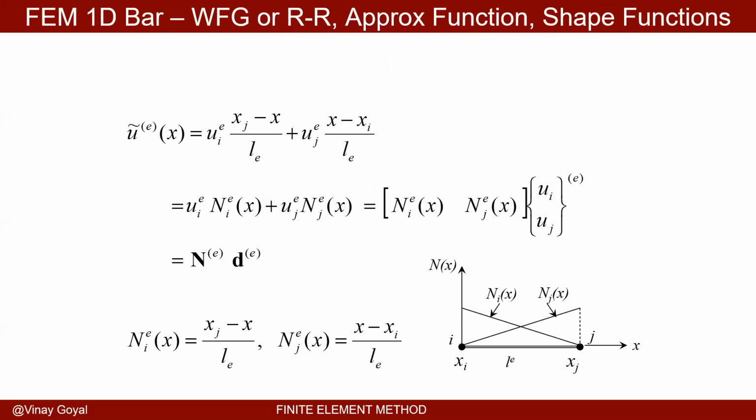So it is kind of convenient to plot them and see what's going on. Now, when it comes to finite elements, it pays off to write everything down into very simple equations. So here are the unknown coefficients. I'm approximating the solution over a domain, over the element E. And you can see here U_i^e is the nodal value U_i. This is the nodal value U_j. And note how this is the shape function.